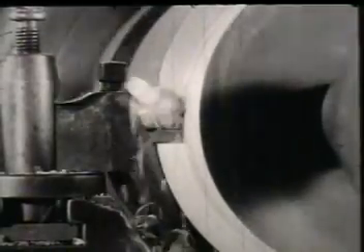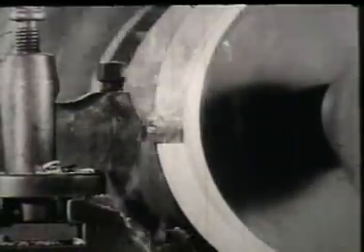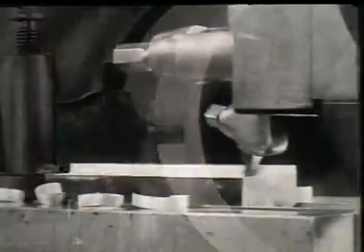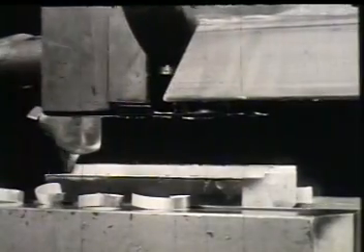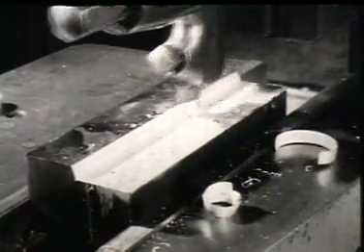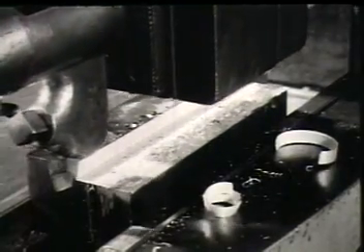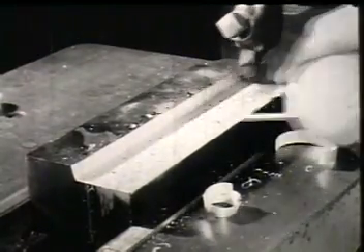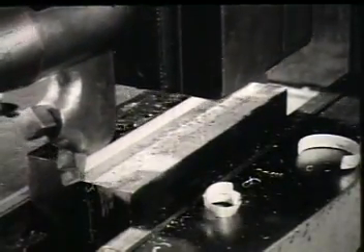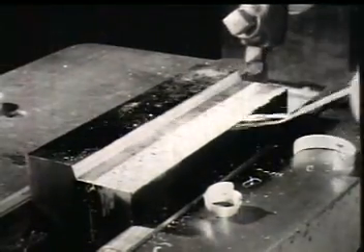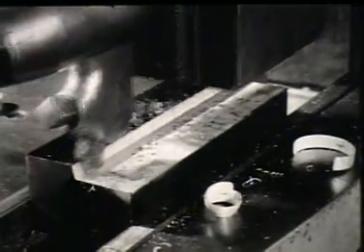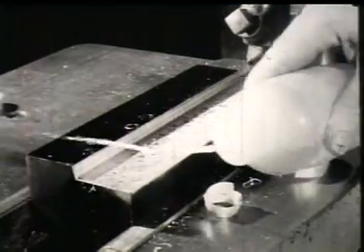When cutting at high speed, it is very difficult to obtain the proper lighting to clearly show microstructural changes. However, metal cutting researchers have known for a long time that the built-up edge can be eliminated when machining at low speeds if carbon tetrachloride is applied during the cutting operation. To obtain some insight into the mechanism of chip formation when no built-up edge is present, cutting was observed when carbon tetrachloride was used as a cutting fluid.